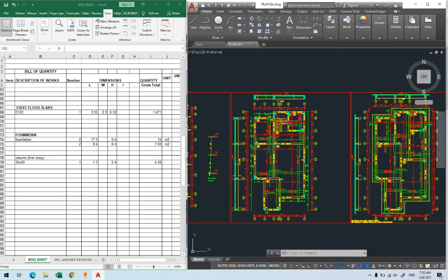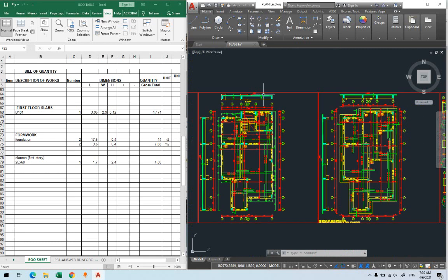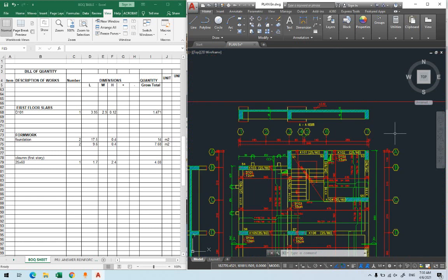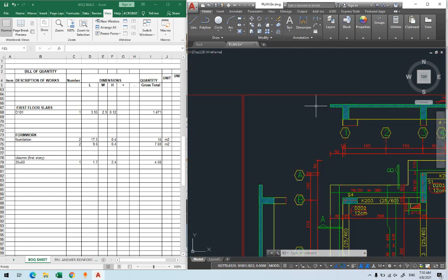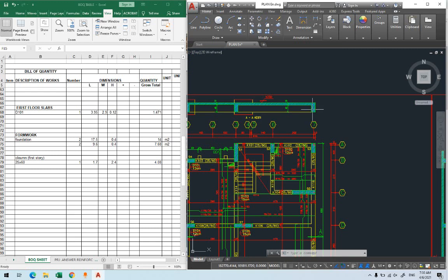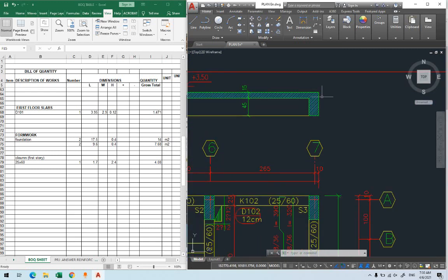Now for the first floor and for the second floor, we have different cases. For example, look at here, the slab does not continue, but for the second floor you see the slab continues. So those will be considered as interior as well. I can consider them as interior, but they are exterior. And by the way that we tell that for formwork, we call them exterior, interior, because of what? Because of the edges here. Because this side is a bit higher, or deeper, than this side here.